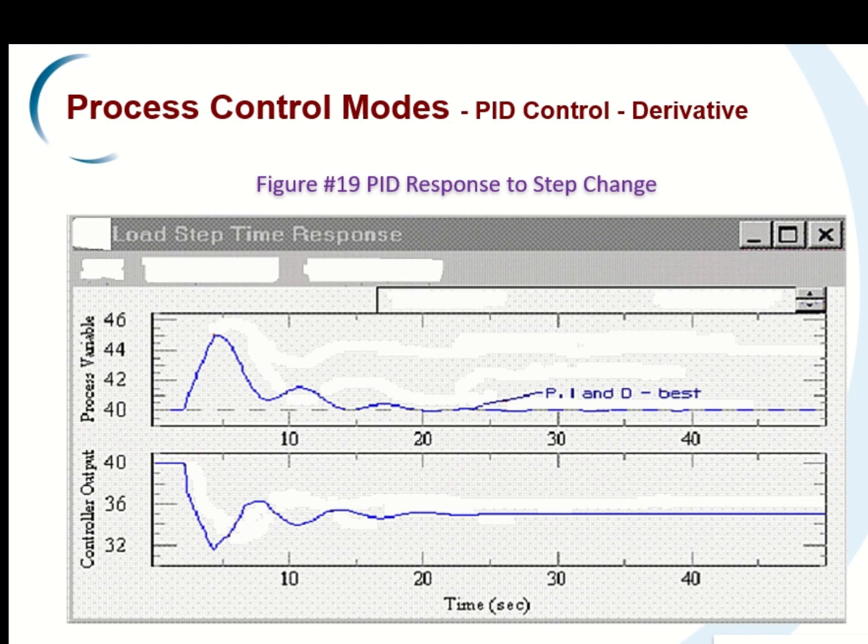If they are incorrectly adjusted, the system might overshoot drastically, leading to uncontrolled oscillation and pieces of equipment dislodging themselves from their moorings. Tuning PID control is an art or a skill which is generally acquired through practice. As an operator, you will likely not be called upon to tune a control loop, but you may be required to make some minor PID adjustment to bring the system to the desired conditions.